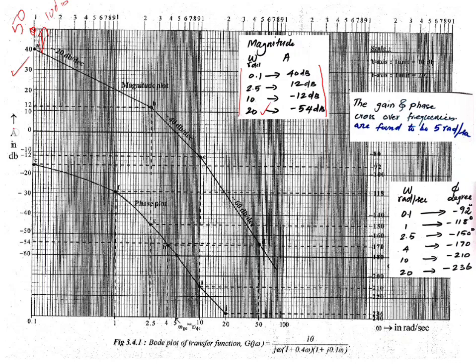So 20 and 0 is here, and I am drawing a line at 0 dB and it goes up to minus 60 dB. Similarly, on the right hand side, for each unit I am considering 20 degrees, and here the range of degree is from 92 degrees to 236. So I'm starting from something around 80 degrees, and each division is 20 degrees, and it goes up to 240 degrees. Now we have to mark the first point, and on the x-axis we have to take